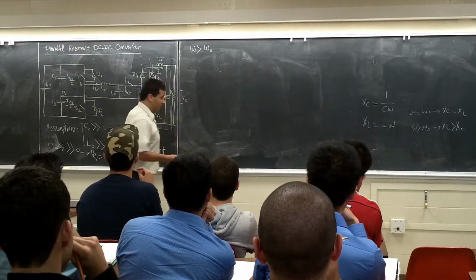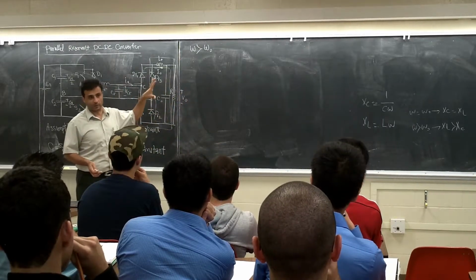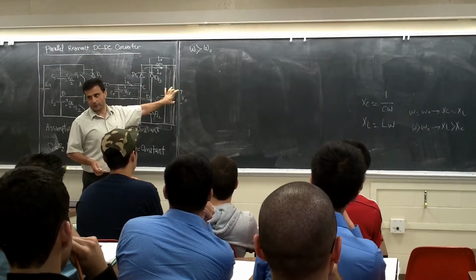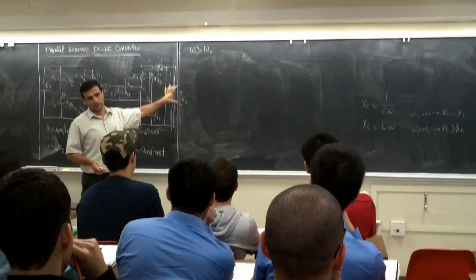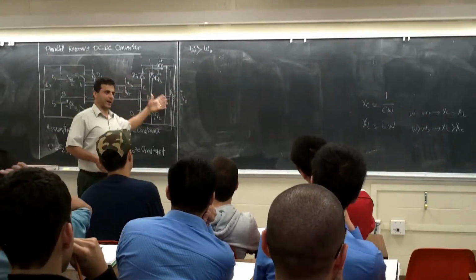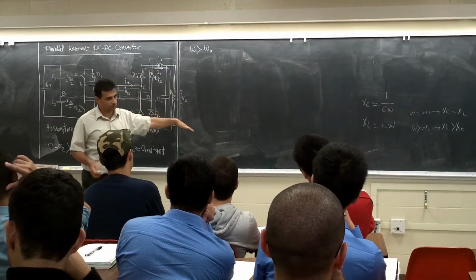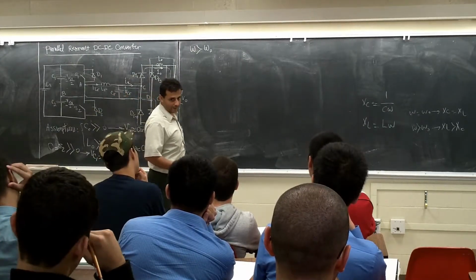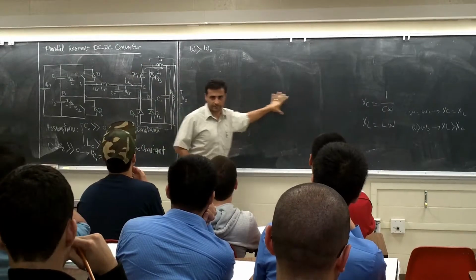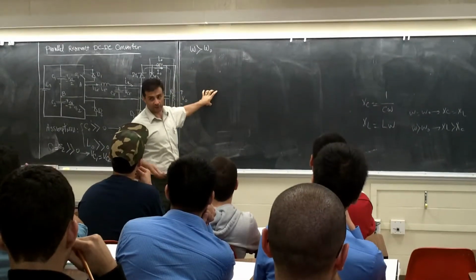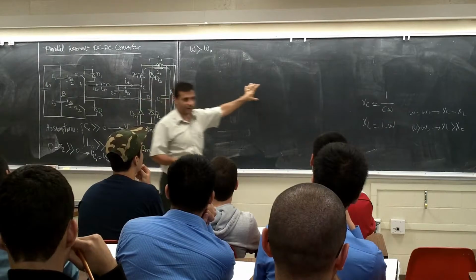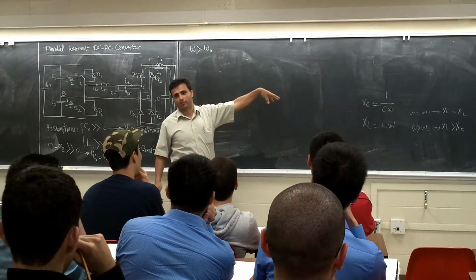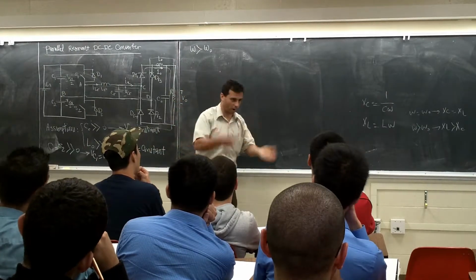My point is, when you get to that point, you are going to use, for example, your car as a UPS. So the battery is here, instead of the resistor I'm putting the battery here, right? Now I'm going to take the power back, so this one has to be bidirectional. Charge, discharge, right? Usually the battery in the car is connected to the drivetrain. To the drivetrain here, there is an inverter, like the inverter is stimulated. And there is an AC motor, that's a permanent magnet motor. So it drives that motor to move your car.